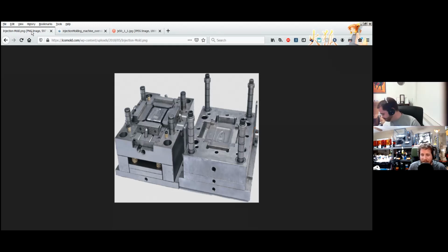SLA is great. It's an awesome process, but it's very, very high detail. You will get parts off of those machines that are injection mold quality. Literally the parts, and I wish I could show them, they're rings because they go directly into casting. They come out of the printer. We rip them off their support.